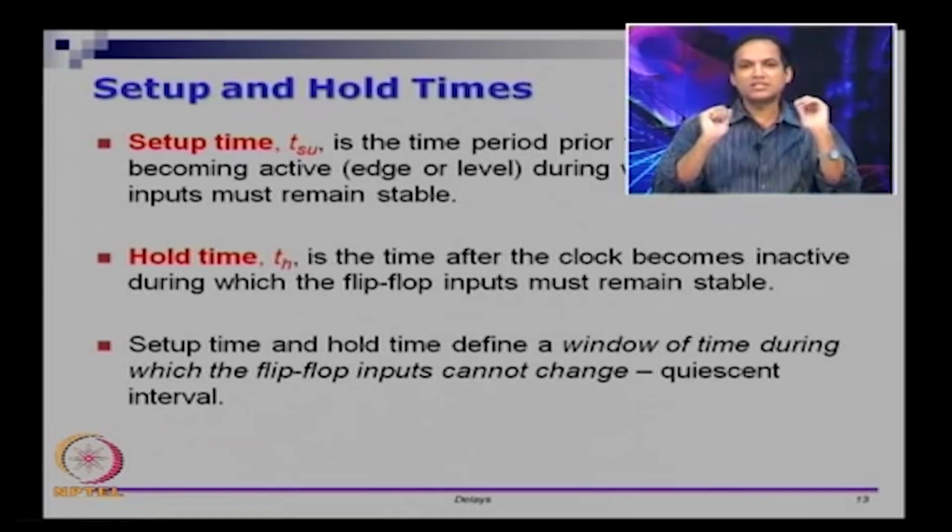And the hold time is the time after the clock arrives. Once the clock comes in, you have to still hold the input steady for some time period, and during this time period there should not be any activity in the input of a flip flop. So this time period is called the hold time.